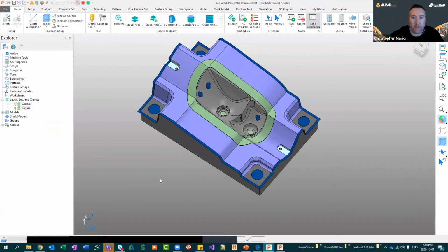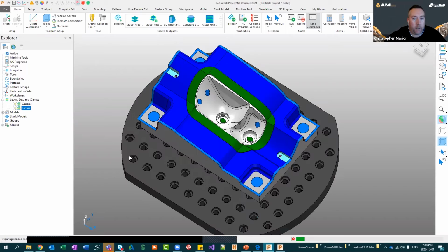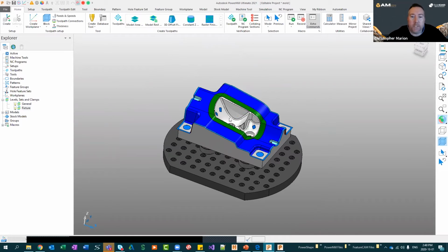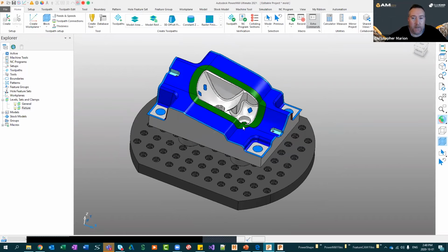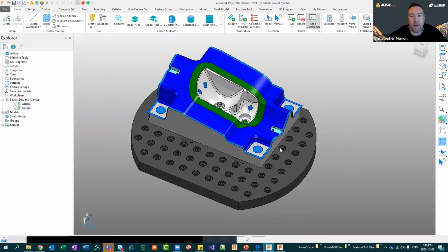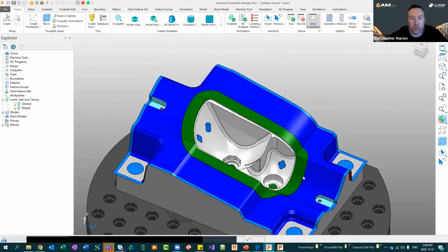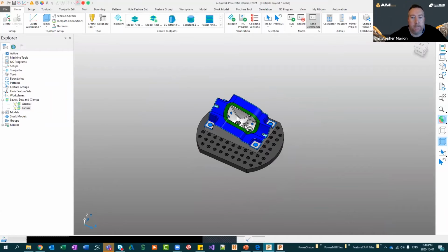Just quickly creating some surfaces that I might need for machining. Okay. And let's go ahead and bring our fixture back in. All right. So once I've gone through and I've capped some holes, put some extension surfaces on. Are they necessary? The extension surfaces might not be necessary, but since I'm roughing, I might not want my tool to come outside the block. And I don't want my tool to go in these openings in the roughing process. Maybe want to cap these and we'll get them when it comes back from heat shrink. We'll get these maybe in semi-finish and finishing.